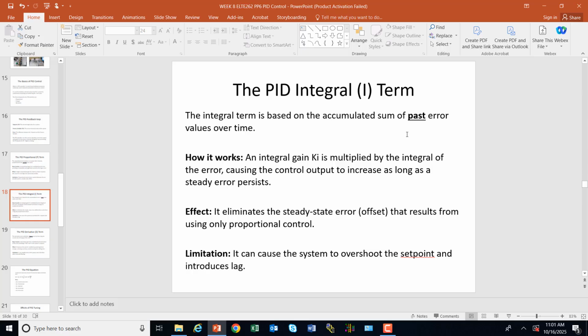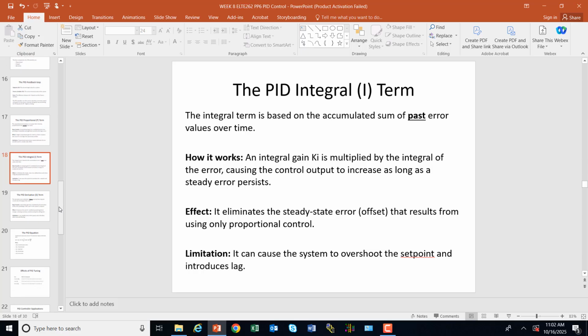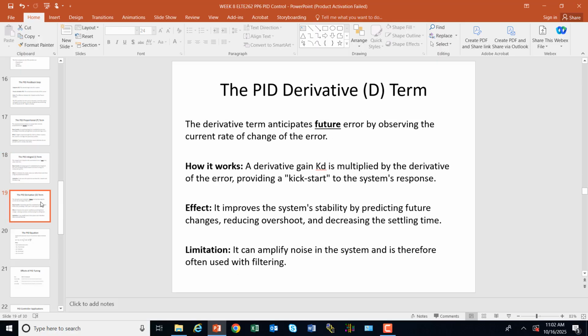And so by the time you get to steady state and you settle in to where the preset value and what you're reading are equal, you might have to still unload the integral value. It might just be full of garbage of accumulated error. And so that's a little bit of a problem that we'll take a look at and see if we can get our lab to work, because our heating process is going to take a little while, and if we load up our integral, we might have some issues there.